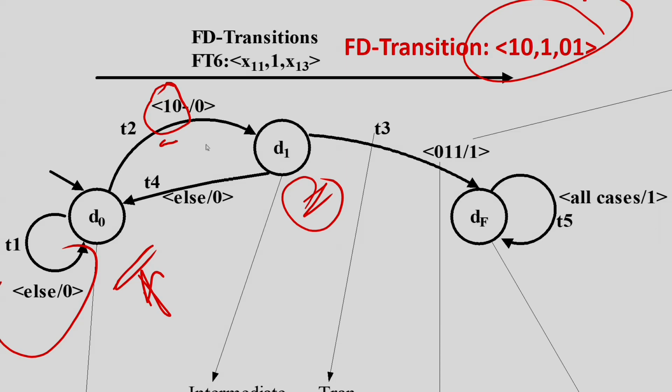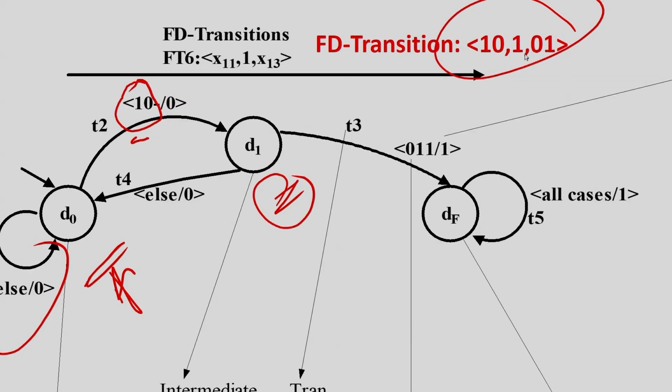But if the fault is there, then from state 1 0, the next state is going to be 1 0 1 and the input will be 1. That is, this part is matching. This one actually corresponds to this, and this input V3 and the output 0 1 is corresponding to 0 1 and 1, and the fault is detected, and you will land in the final state where the output is a 1. This is the output of your tester, which says that it is a fault, right.